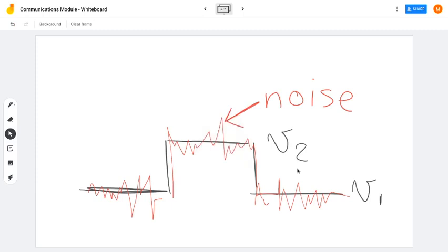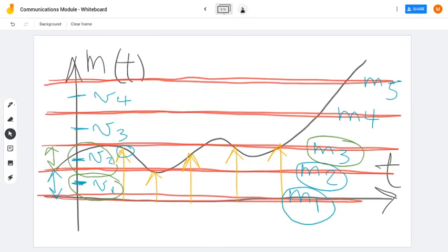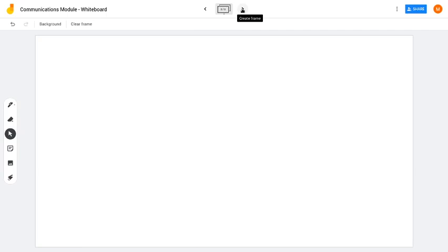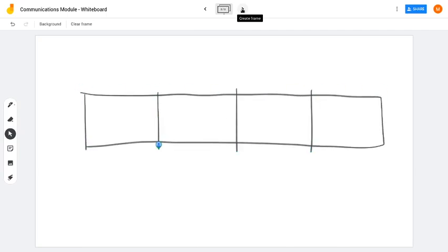And in order to understand this, let's move to our whiteboard over here, and let's say we will have an example. Let's say the simplest form of error control coding would go like this. Let's say we have a word of 8 bits we are going to transmit, and let's say we will agree that we will keep the last bit as a flag we are going to use, and it will not carry any data.